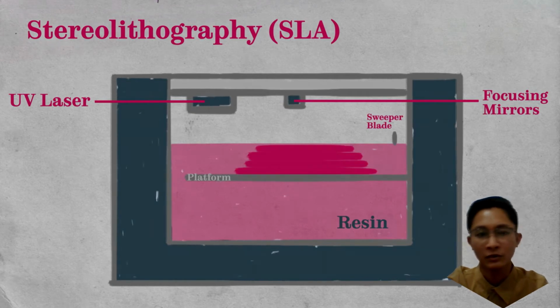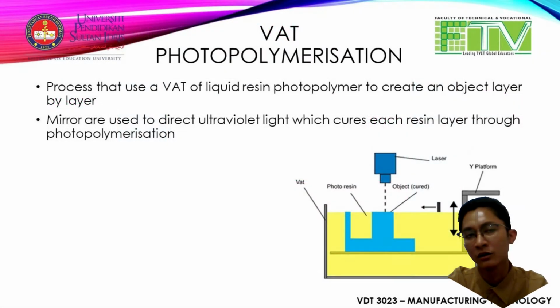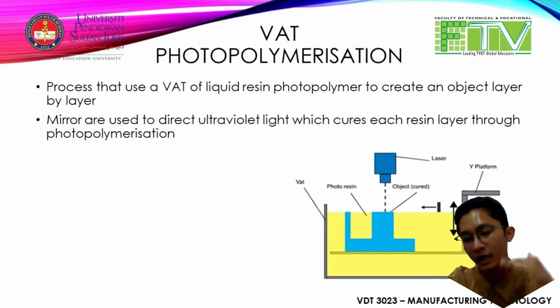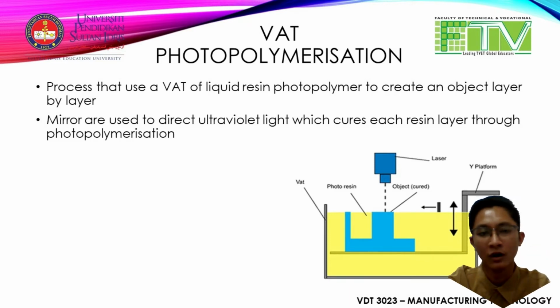This process uses a combination of two molecules called epoxy and acrylate by using UV radiation. The printing process is carried out with a UV laser. We remove the liquid and the process is done layer by layer. This vat process is very fast and quick.